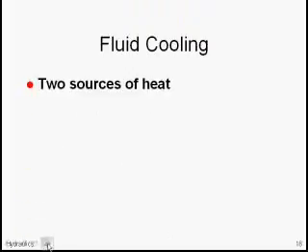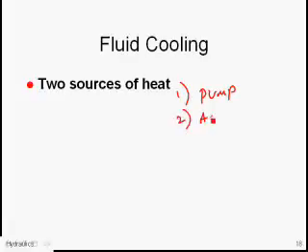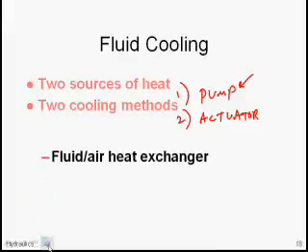Fluid cooling. The problem with hydraulic systems is that they generate heat. Some of the energy that's taken off of the engine is not converted into hydraulic energy at the pump. Some of it's converted into heat. Although it's lubricated, there is some friction. So the two places you're going to get heat: the number one place is going to be the pump, and the number two place is going to be the actuator. But since the pump is supplying power to all the actuators, it's concentrated there. So usually the pump gets the hottest. But it's going to heat up the fluid, so we're going to have to do something about cooling the fluid.